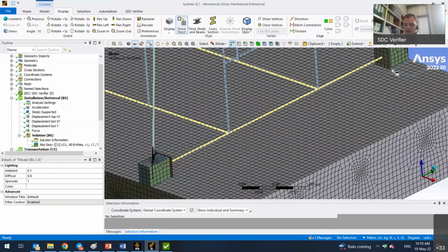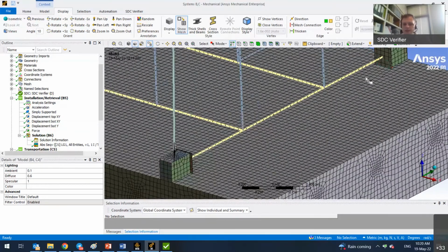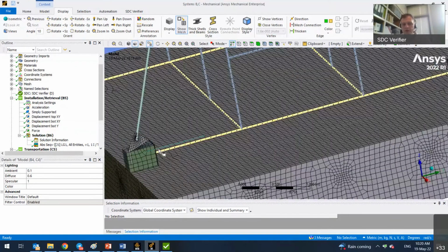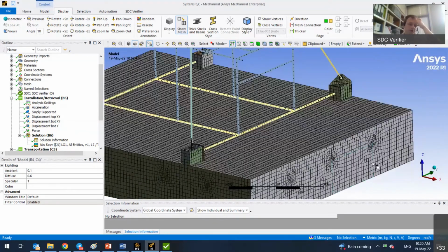under the center line of this beam, and make sure that the mesh size is exactly the same for the beam and for the plate, and just merge the nodes. So this is an example model, so I didn't pay that much precision and attention to the details, but yeah, it's a good question, and this connection is important for the general deflection and behavior of this structure.